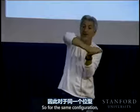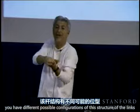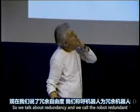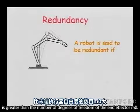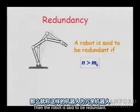So for the same end effector configuration, you have different possible configurations of the structure, of the links. And that means we have redundancy. So we call the robot redundant if the number of degrees of freedom of the robot, n, is greater than the number of degrees of freedom of the end effector, n0. So if we have this situation, n0 here is equal to 3 and n equal to 4, then the robot is said to be redundant.